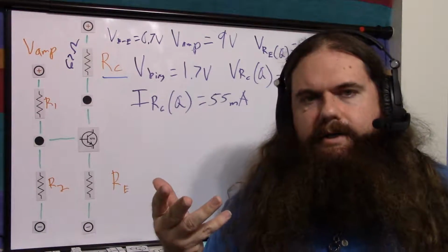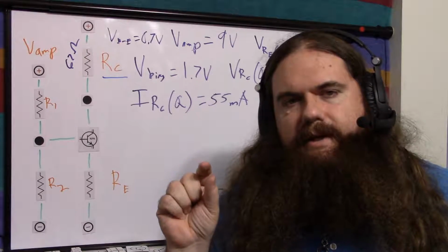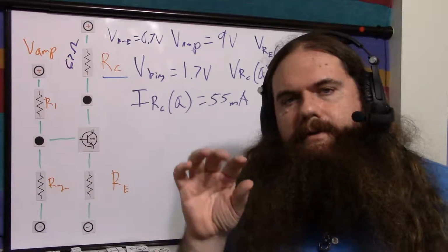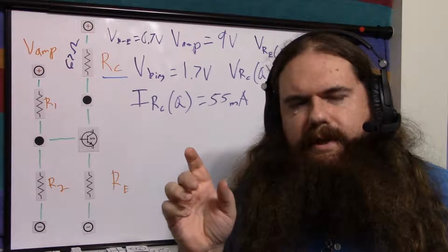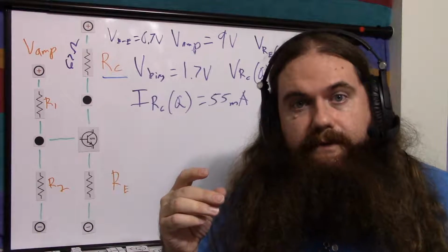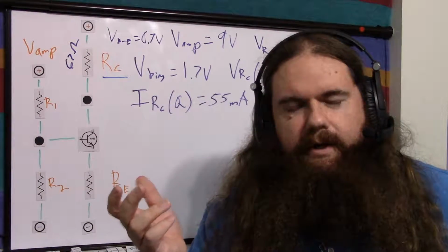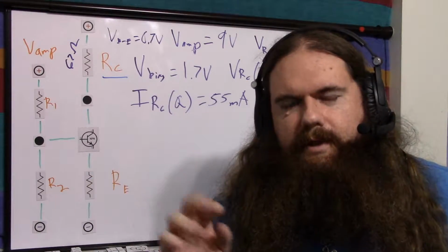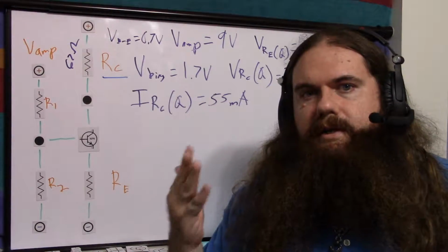So if I look on the datasheet for the 2N2222A that I'm going to use, and this was just one manufacturer, the minimum range is around 10 milliamps, 30 milliamps, ends up being around 70-ish, 75, go up to 150 milliamps. This is with 10 volts. 150 milliamps ends up being 100, but those are minimums, and they go up to 300. So, lots of variance.